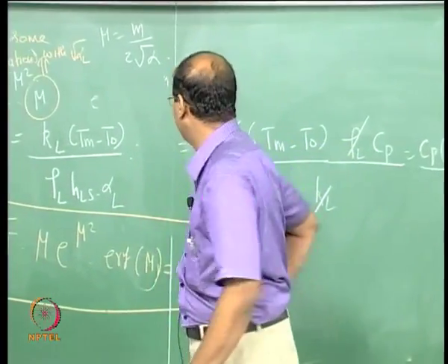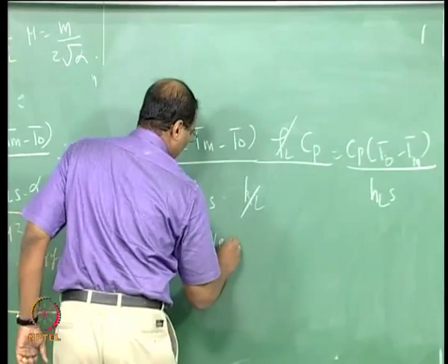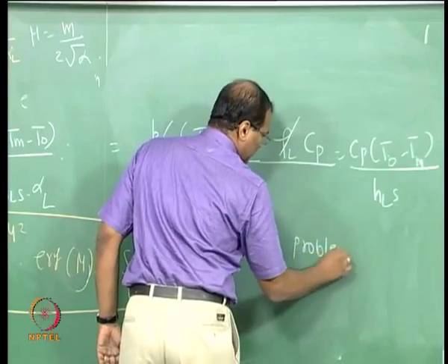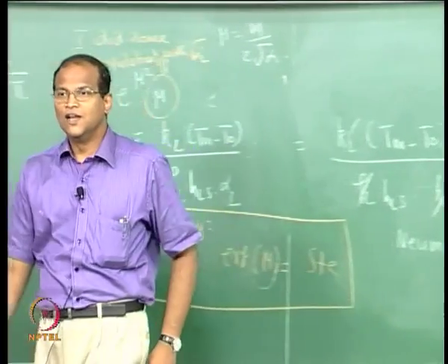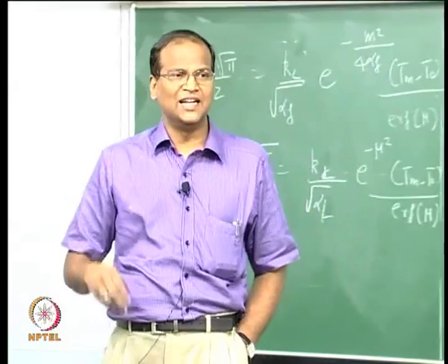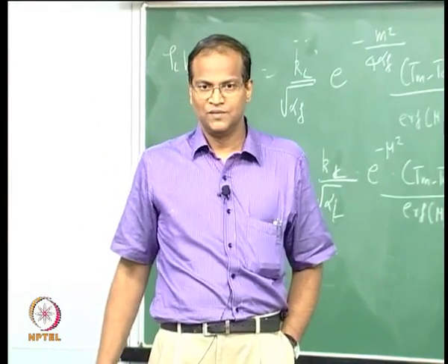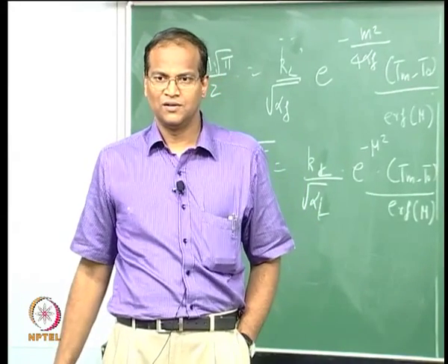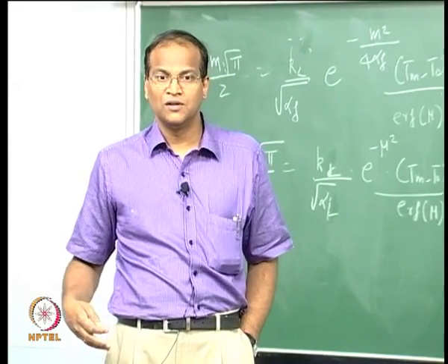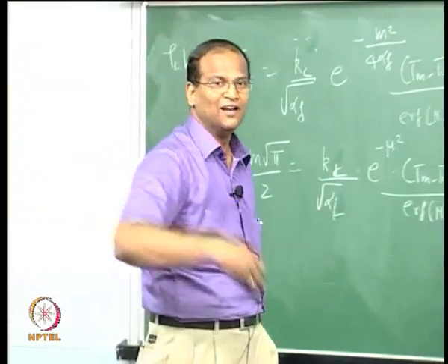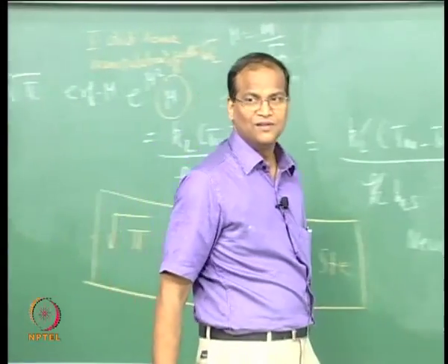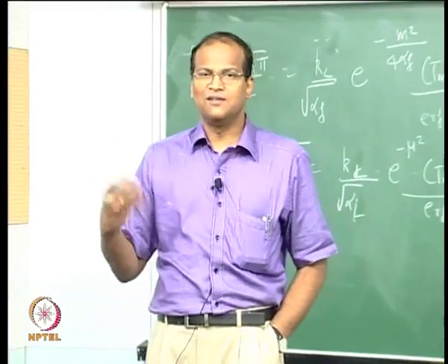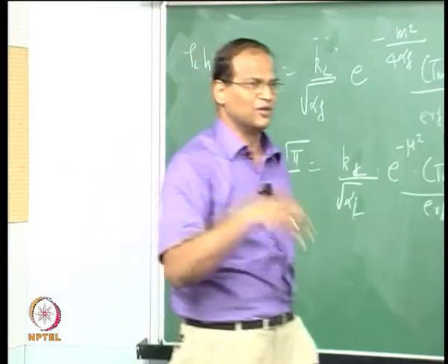What is the Neumann problem? In the Neumann problem, the Ti is less than Tm. Initially, the body is at a temperature lower than the melting temperature, everywhere at Ti. There will also be sensible heat, and you will have to consider conduction in both the liquid phase and the solid phase.